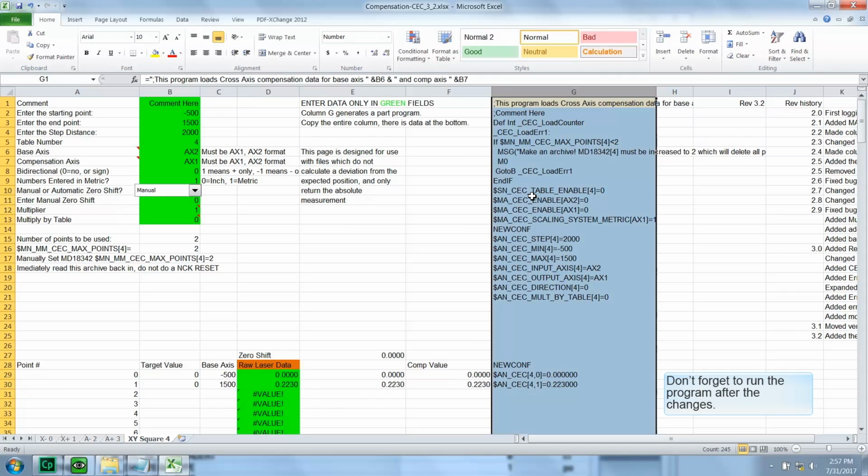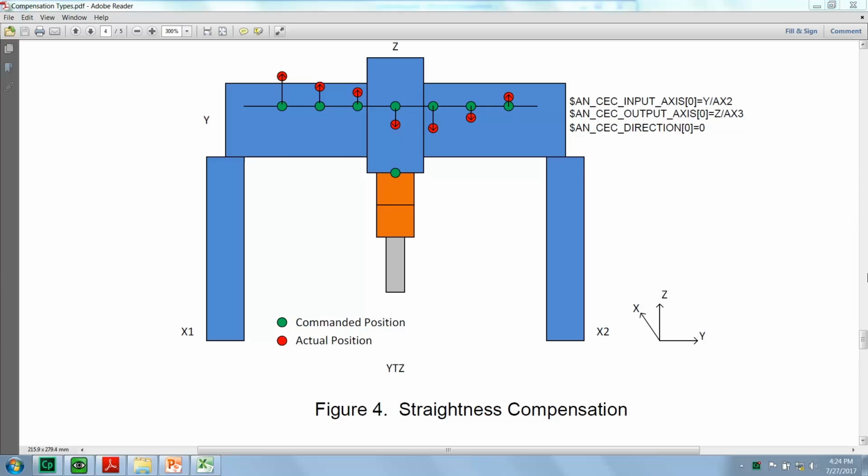This can get a little bit interesting sometimes because the Renishaw convention is based on the initial direction of travel for the plus and the negative sign, and it's also a perspective thing of which way you are looking at the XY plane. Because this can get a little bit confusing in practice, I just set it up, try it as positive, and if I'm wrong, I flip the sign, and it usually takes me less time than trying to think about it. So now we're going to talk about a few special cases.